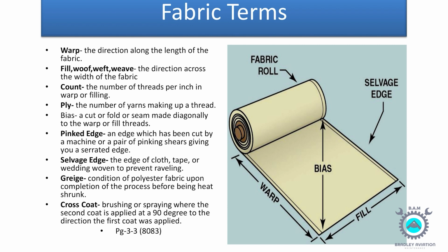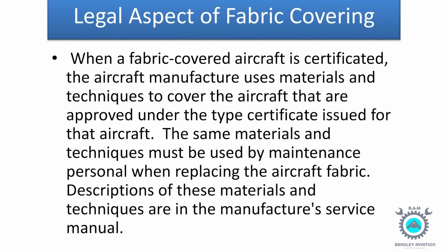Legal aspect of fabric covering. When a fabric-covered aircraft is certificated, the aircraft manufacturer uses materials and techniques to cover the aircraft that are approved under the type certificate issued for that aircraft. The same materials and techniques must be used by maintenance personnel when replacing the aircraft fabric. Descriptions of these materials and techniques are in the manufacturer's service manual.